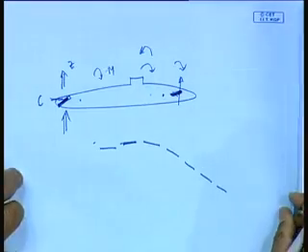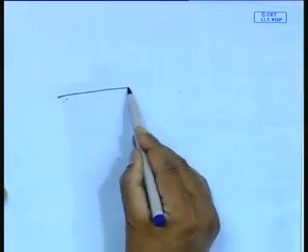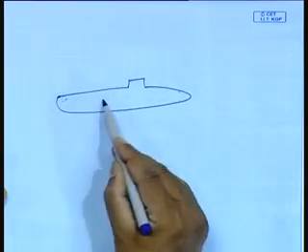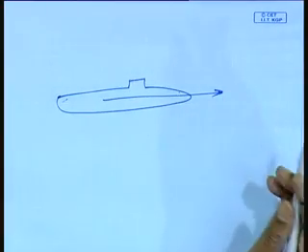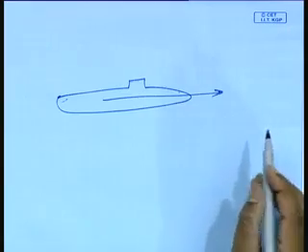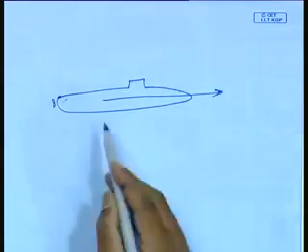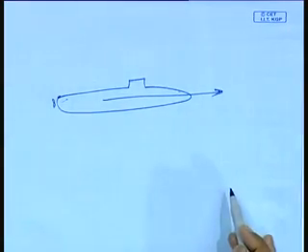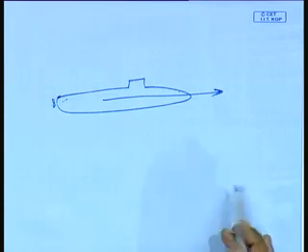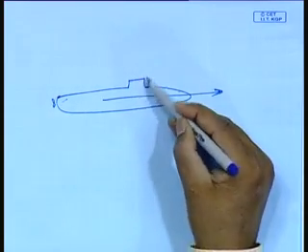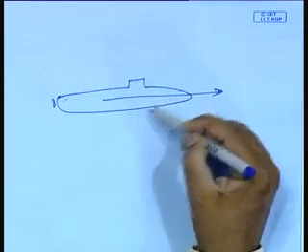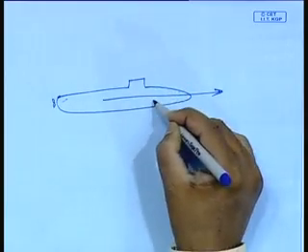See, now the other thing I want to tell you for a submarine is that in order for you to maintain level depth, you want to go in a straight line. You will see that you can never achieve a straight line. Suppose you have no controller, it will always either go up or go down. Why? Of course, obviously one can tell there is no symmetry here, so there is an asymmetric moment that comes. Normally it is designed to go up.